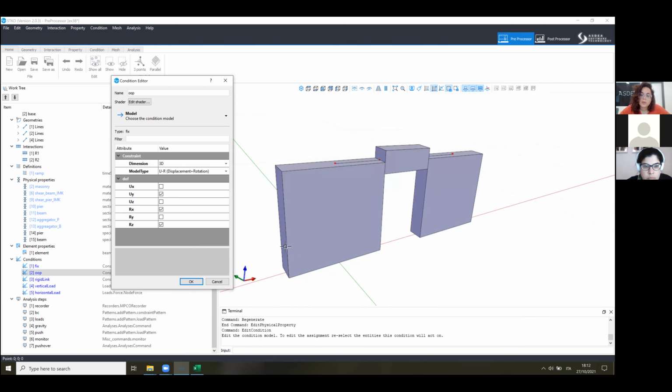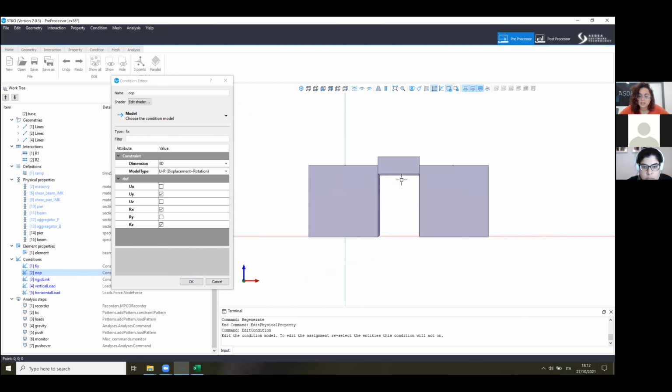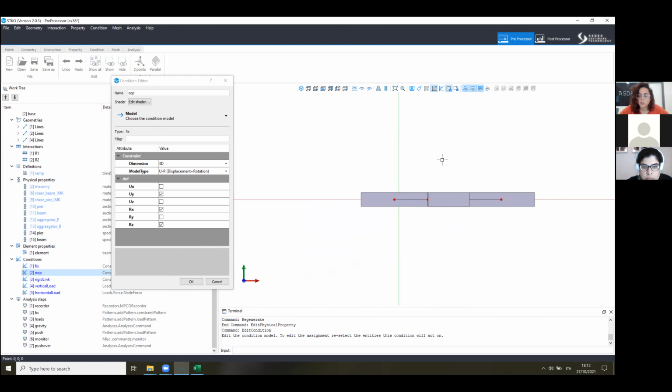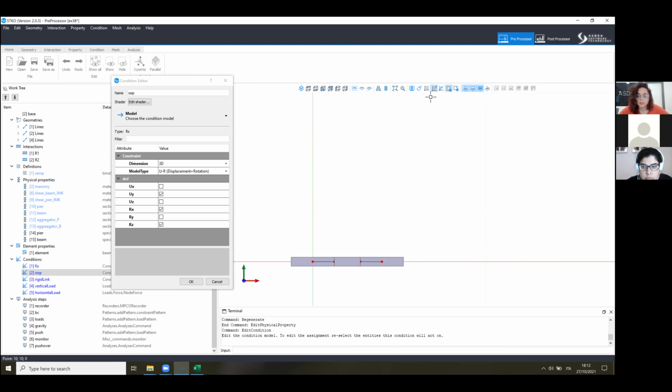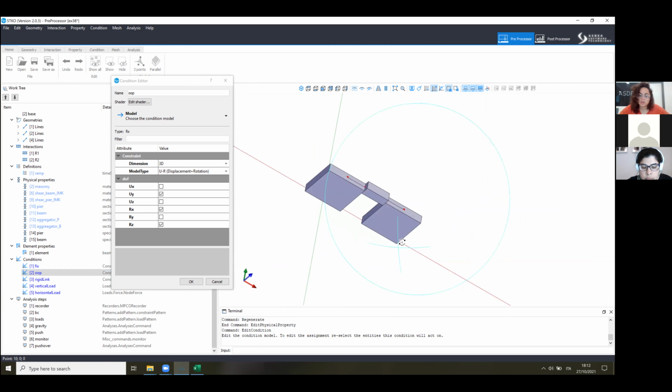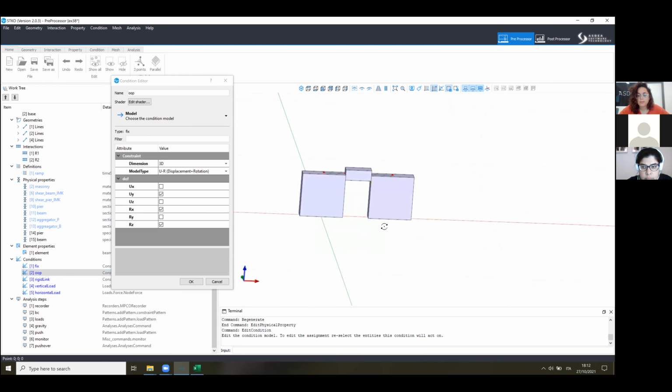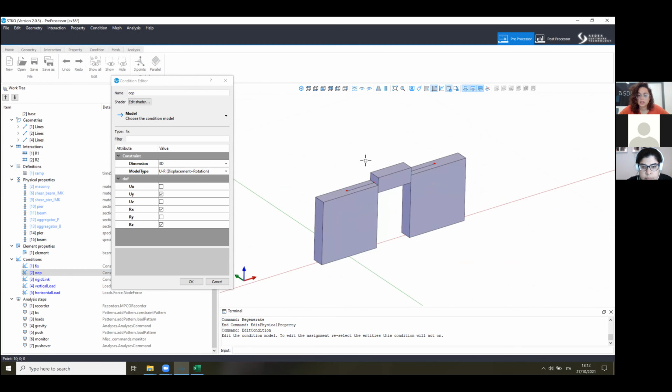I would suggest that you use 3D elements and work on the XZ plane instead of the XY plane. I don't know if you guys ever tried, but if you use the 2D elements, you have to work on the XY plane in STKO. Otherwise, nothing will work in the other planes. But anyway, I would suggest you use the 3D elements, work in the XZ plane, and fix the movement of your elements in the out of plane direction.